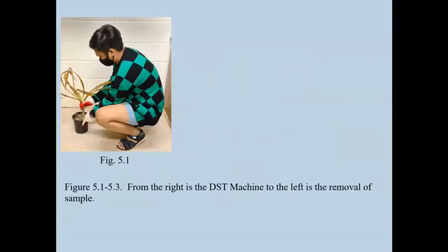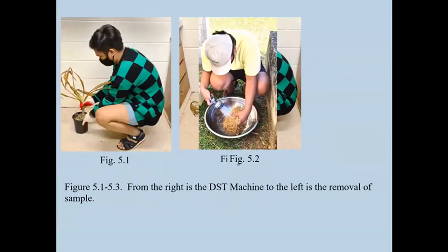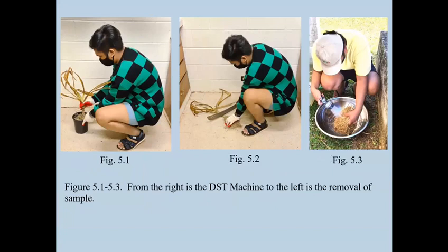For root tensile testing, we begin by removing the root system from the plant and washing off the stones and soil. Then after drying the roots, we chose the roots that are at least 25 centimeters in length from the root system. And with the caliper and the ruler, we measured the root diameter and length.